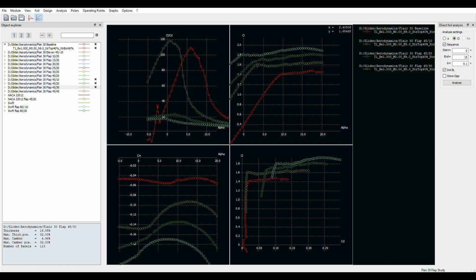That was the big mistake. So I'll say it later and I'll say it here. Never, never, never hinge your control surfaces forward any more than, say, 25% the chord of the flying surface. And that could be a tail, a wing, anything.